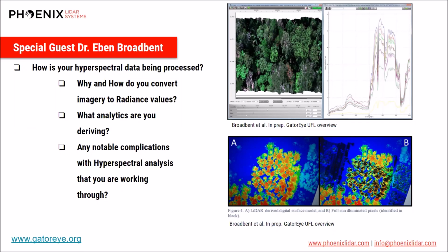But in Florida, and we've worked in a lot of places, a lot of the time there are these puffy clouds, and they will shade your sensor, and then they're not shading, or it's a totally different kind of shade over where the drone is flying. And once again, it's time synchronized, but it's producing bad data.